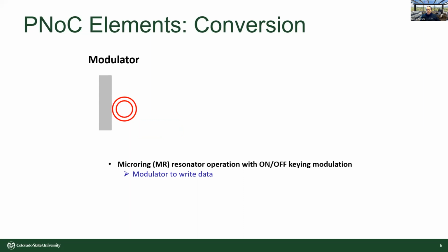So ultimately, what we want to do is send digital data over this optical link, which is basically sending data over light. The way that this happens is you need to use some sort of optical device, and you need to use some modulation mechanism. Here, I'm talking about using this microring resonator device, which takes in this bit stream, and you can have this bit stream imprinted onto wavelengths of light. For example, this red-colored microring resonator is working with the red-colored wavelength that's tuned for it. On-off keying modulation is one of the techniques you can use. It's fairly straightforward. If you want to send a 1, just let the red wavelength pass through. And if you want to send a 0, just absorb the red wavelength, right?